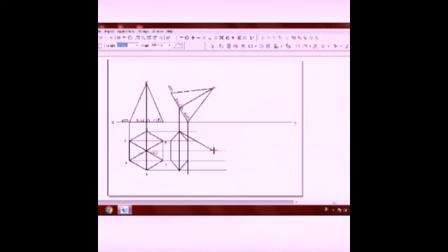Exact intersection point, and then to the base, and similarly another base point to the apex, to the another base. Two more are remaining there, to the apex and back to the base point. So all the 6 slant edges are over, but it is resting on that particular edge, so that should be a dotted line. Select that line